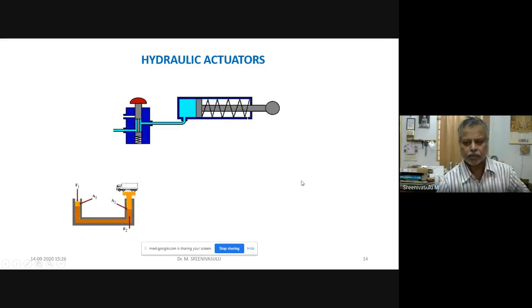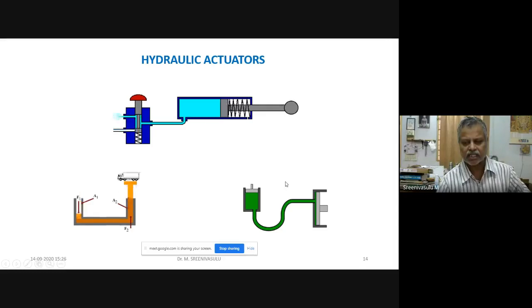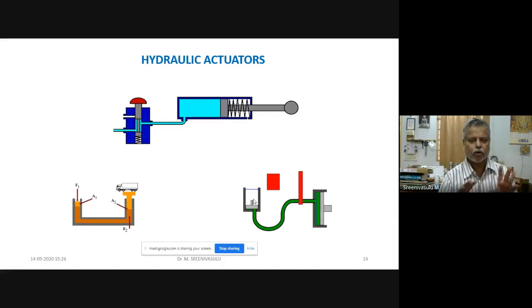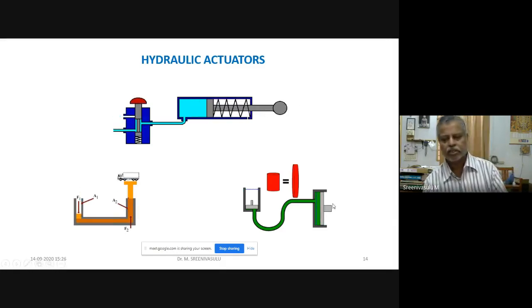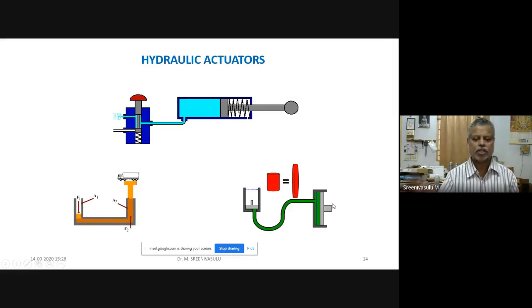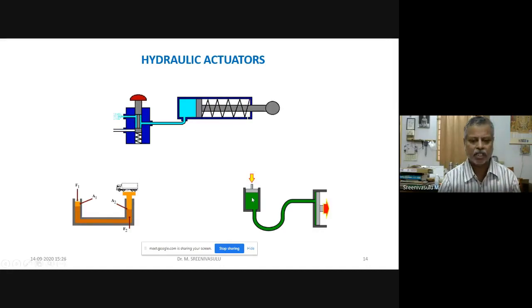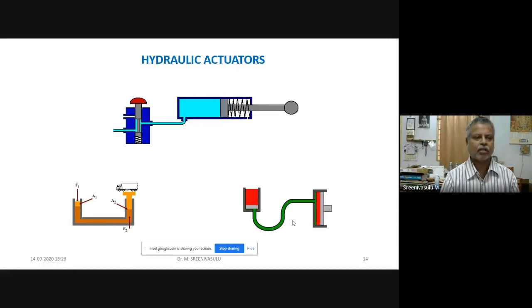Here more displacement was there and here less displacement was there. Here, pressure multiplied by area is the force. Even here the same. So that is how the force is getting balanced. The same amount of force is getting transported through the fluid from here to here. So the game they are trying to play is with the area of opening. Here a lesser area has been accommodated in the beginning. Here more area has been accommodated.